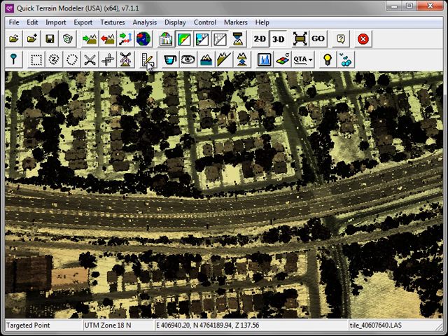To begin measuring, click on the Place Mensuration Line button. To start your mensuration line, you can press the S key to create the first point, or simply left-click. You can create additional vertices or points along your mensuration line by left-clicking. If you need to navigate, specifically pan, while generating the mensuration line, simply hold down the Alt key.